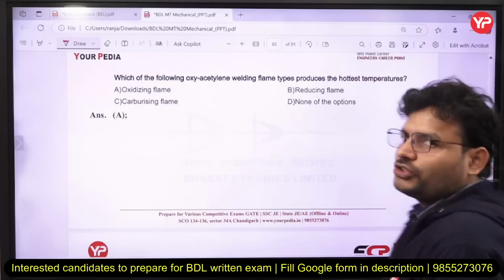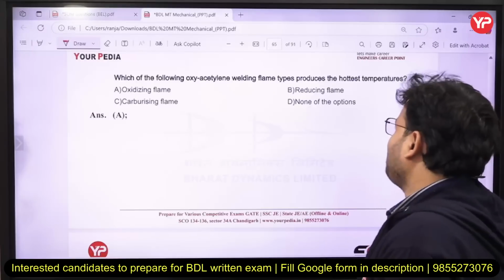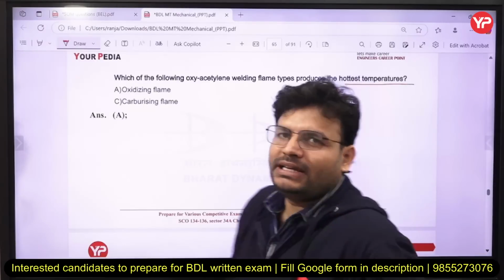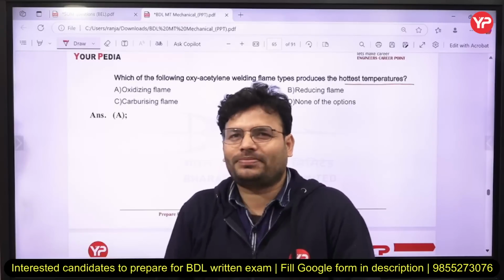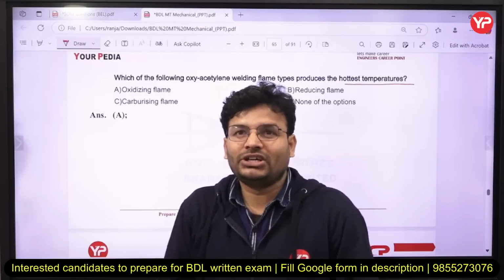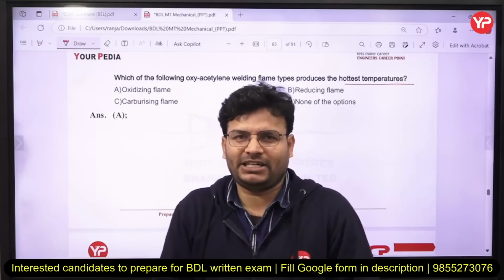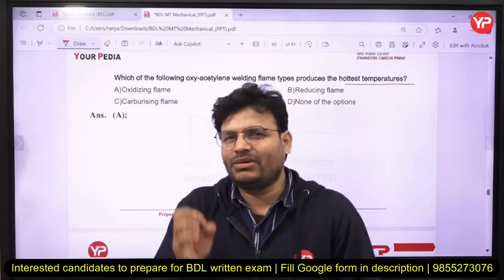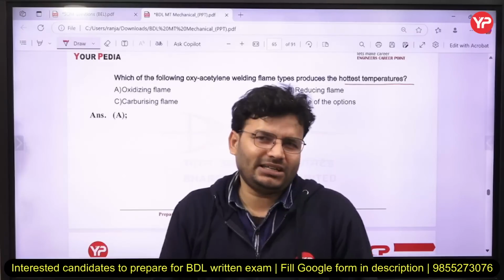That is again a question from welding. Which of the following oxyacetylene welding flame types produces the hottest temperature, right? Which will produce the hottest temperature? So we can say, in case of oxidizing flame, what is happening, my dear friends? The content of oxygen is more. In fact, if 1 mole of acetylene, then it can be 1.2, 1.3 mole of oxygen. So oxygen is more. So there will be a proper burning of the acetylene. If the proper burning takes place, my dear friends, the heat generation will be the maximum. So if it is going to ask, maximum temperature approximately 3400 degrees Celsius, sometimes more than that, you are going to get in the oxidizing flame.